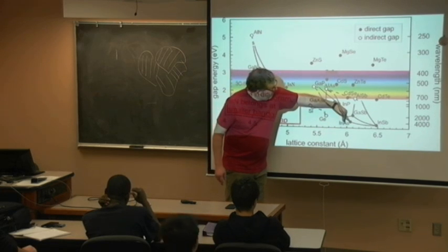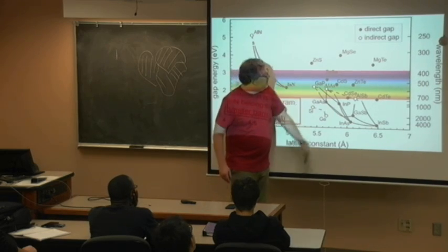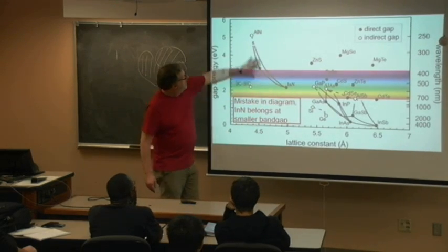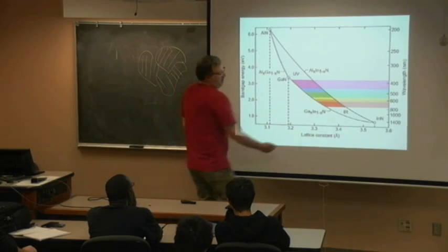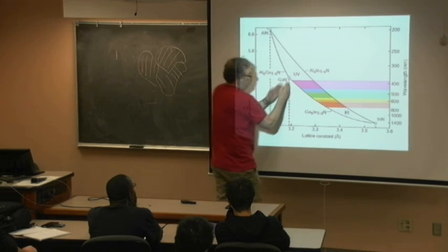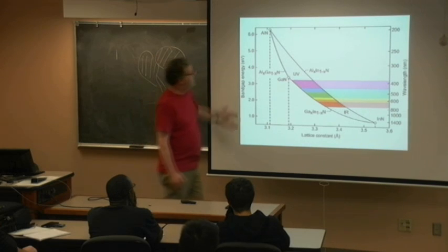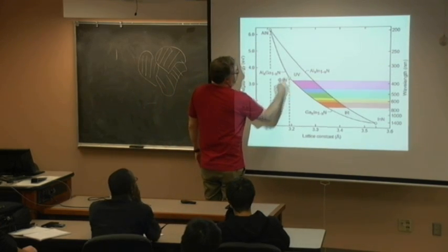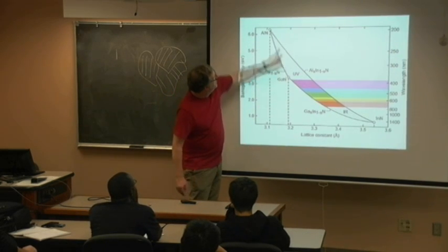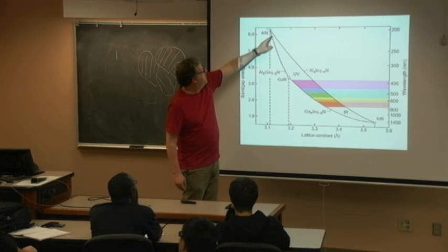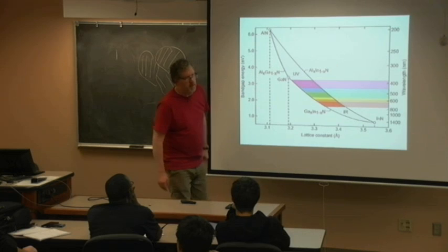You go this way, it's indium rich. There's a limit to how thick you can grow it. If it's gallium rich, there's a limit to how far you can grow it. Here's your LED market here. And so there's a limit to how much indium you can put on, because these are now huge. This is even amplified compared to the silicon germanium world. And so you can usually only deviate a little bit about that. We just came out with a paper, actually, where we were doing these two. And it's severe. I mean, we were limited to like 2 or 3 nanometers of this on this to keep it within constraints.